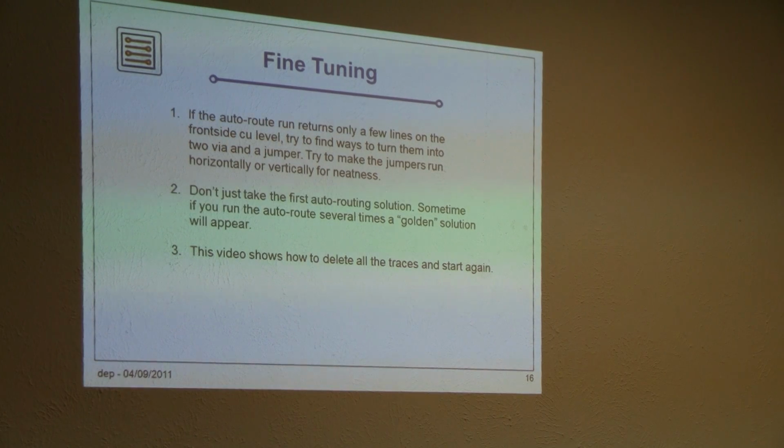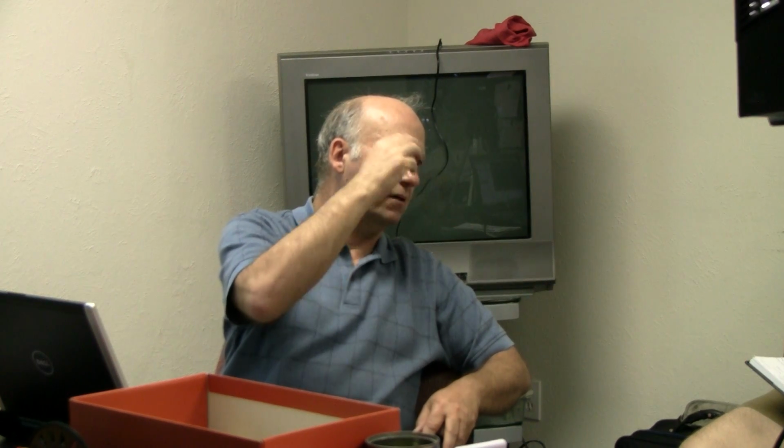That's when you're routing the wire? Yes. Otherwise, you've got this wire that's all green, all backside, except for one red, and you want to get rid of it because you could make a one-sided board if you didn't have that one red wire. As you delete the red wire, you'll get, what do they call that, the rat's nest. You'll get a rat's nest line.